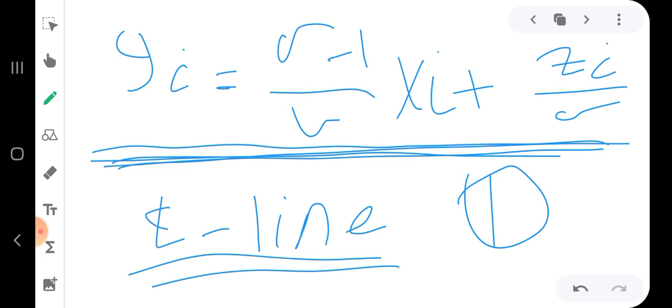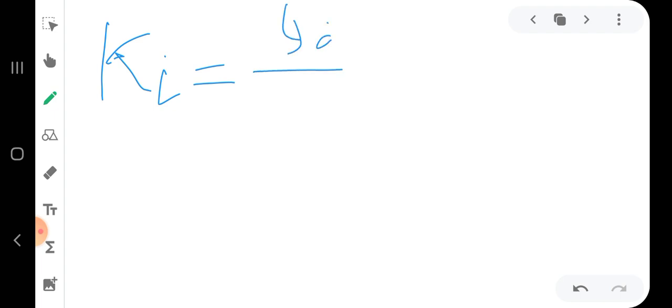The second equation will be the equilibrium relationship equation. And how are we going to find this relation? Okay, first let's define something called the distribution coefficient K, which we have discussed in chemical engineering thermodynamics. This distribution coefficient is defined as Ki is equal to the composition in the vapor phase Yi over the composition in the liquid phase, Xi.